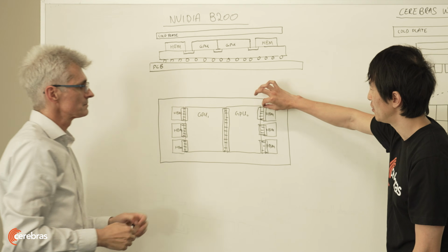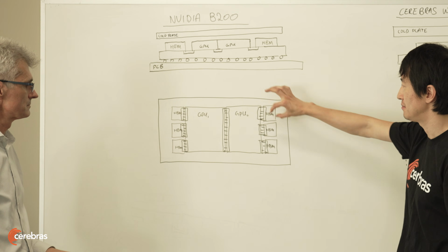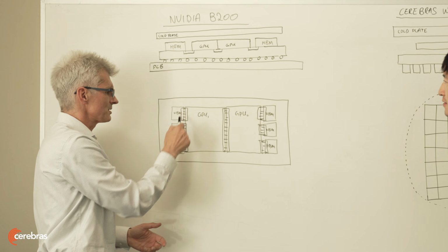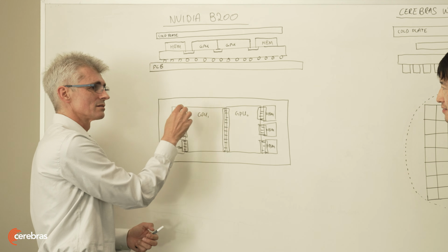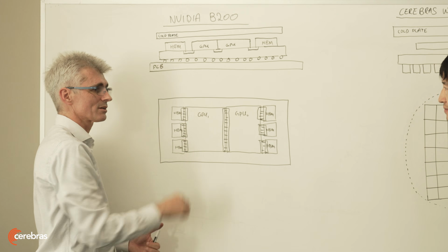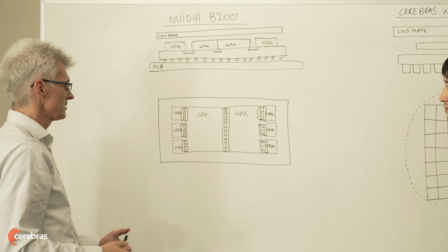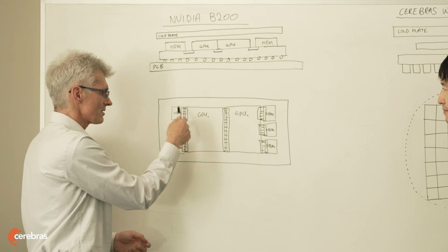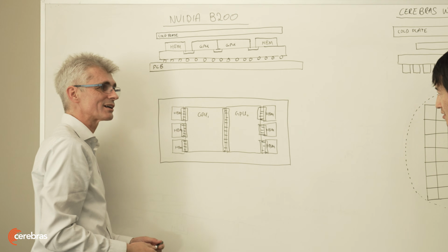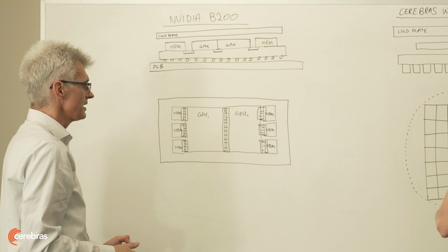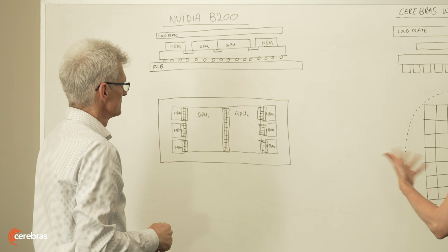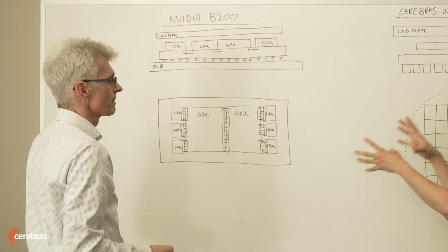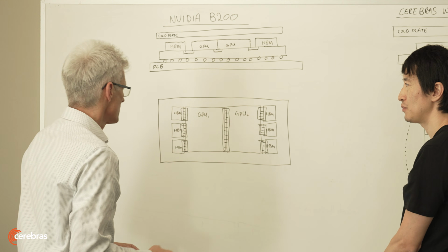What kind of scale are we talking about that we have to align these components? So typically the pitch here is 10 to 50 micron for those interconnections. That's a typical scale for those. The HBMs are getting smaller and smaller at each generation. Align precisely. And that becomes a nightmare of alignment. Okay, I hear alignment is part of the issue. I also hear thermal expansion differences are part of the issue. What's going on there?